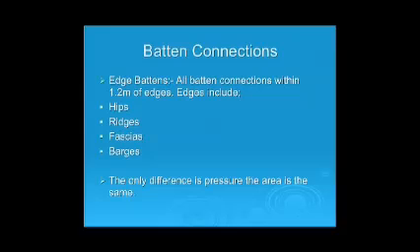is the pressure. The tributary area is going to be the same. It's the pressure that's different. That's very important you understand that. People get this confused regularly. Now, when you have a look at what I've just said, and that bottom line, the only difference is pressure, you have a look now at the difference in the pressure on table 9.5. Let's look at N3 sheet roof, for argument's sake.